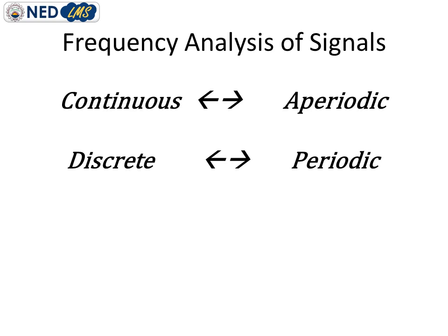So if your time domain representation is continuous, then its spectrum must be aperiodic. But if your time domain representation is discrete, then your frequency domain representation will be periodic, which is written on the slide. Moving on to the next parameter, if your time domain representation is aperiodic, then the transform pair is continuous, which means your frequency domain representation will be continuous.